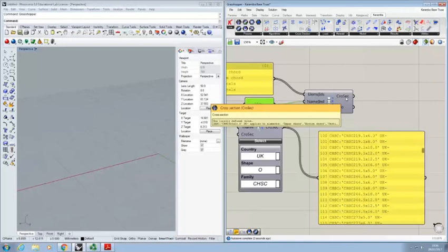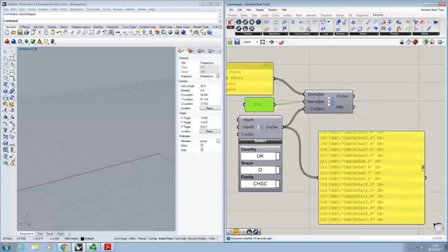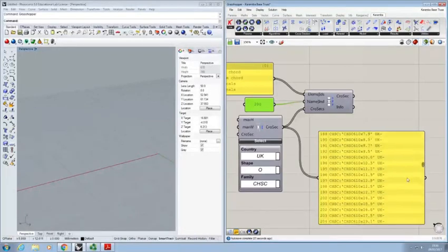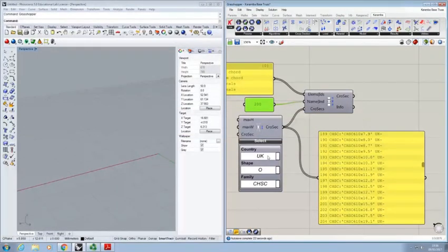You're going to see that I've just selected the CHS 610 by 14.3, and I've applied it to all the different parts of the truss, the upper chord, bottom chord, etc. You scroll down in that list to 200, that's the one we've selected. So as I said, this name input here is the index that's being selected from whatever list you have here of cross-sections.